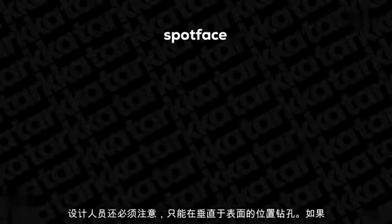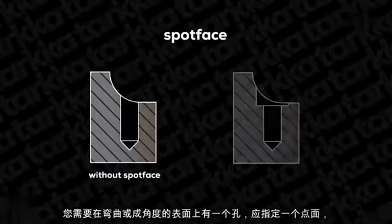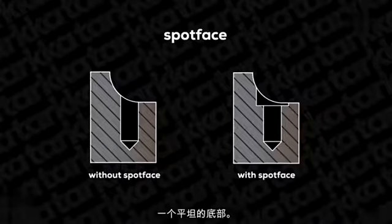The designer also must be aware that holes can only be drilled normal to a surface. If you need a hole on a curved or angled face, you should specify a spot face, which creates a flat bottom to work from.